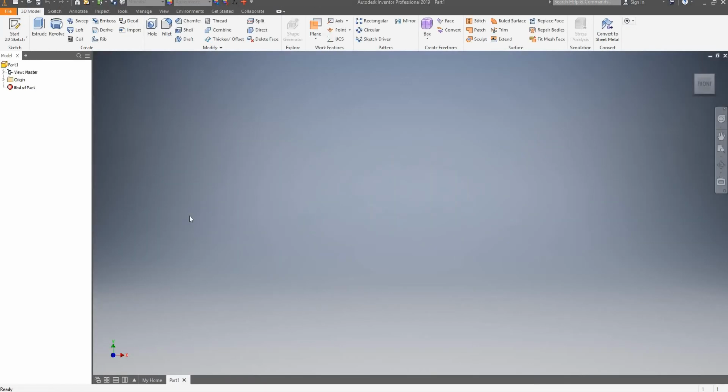Okay, so the first thing to mention is, what is parametric modeling? Unlike AutoCAD and other software that are not parametric, here everything you draw or generate goes here in your model tree, which is like a logbook that saves every step you take. You can basically edit anything that you've previously done. You can go back in time and change diameters or lengths and edit any feature that you would like. Otherwise, in non-parametric software, it's normally not so easy to change features that have been previously created.